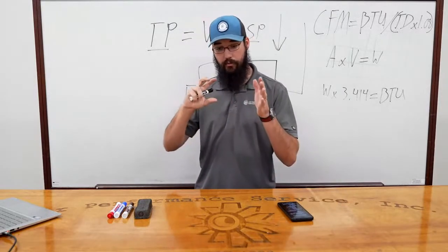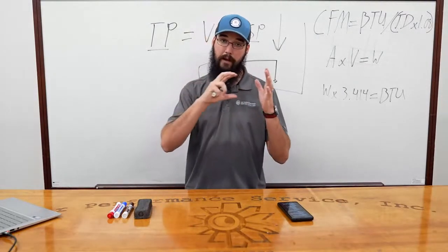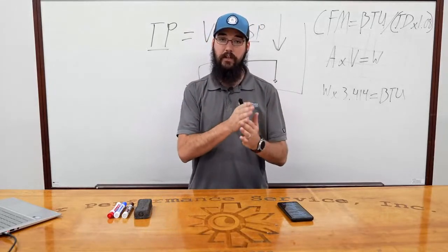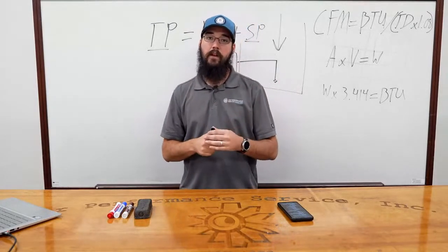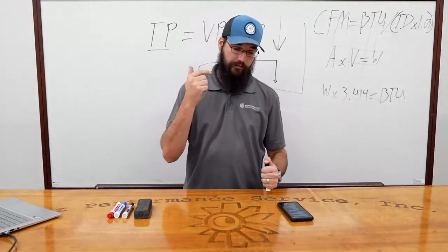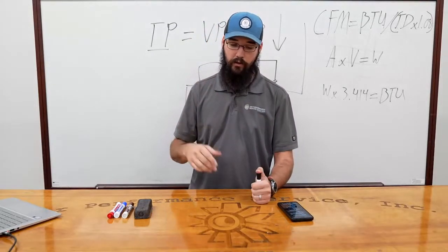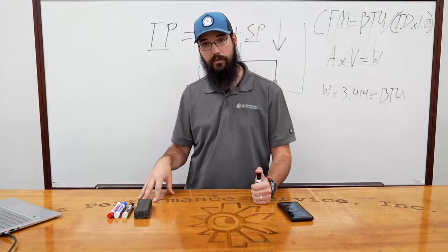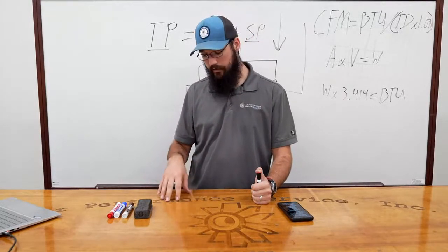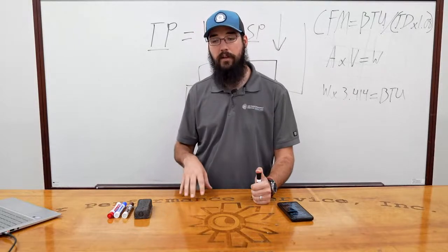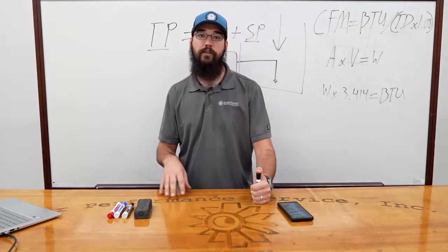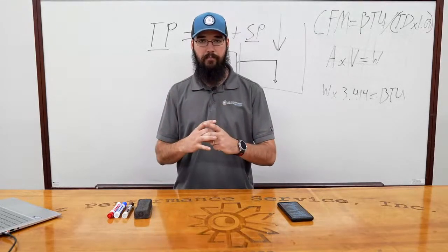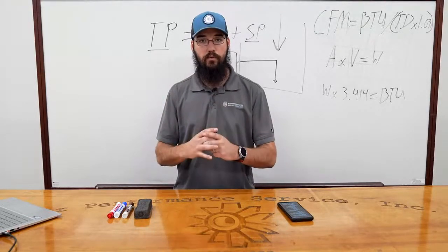You're supposed to, upon installing it, thread those in and set them where they're meant to be. I've gone through a lot of buildings where whoever commissioned the building never set those, and what it ended up leading to is they had a lot of problems because none of the units were moving enough air, because the smaller you make that drive pulley, the slower everything's going to move.